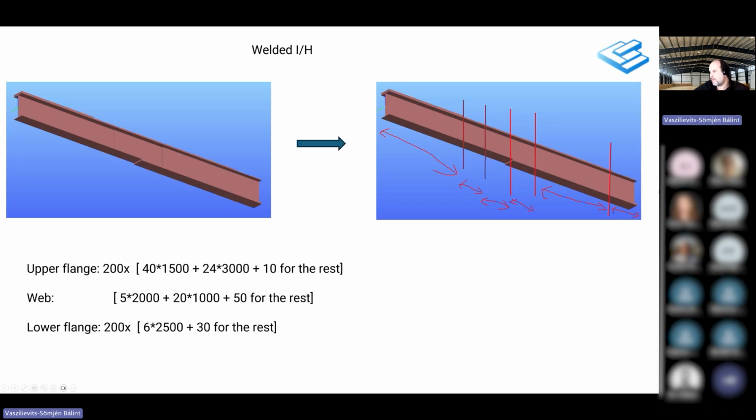Place them on the same reference line, solve the problem of eccentricities because these are strongly monosymmetric. When I place them, the same situation happens, that they will be automatically adjusted by the reference line, which is the center of gravity, which is not in the middle of the profile. Therefore, it looks very messy when I first made it. Up to now in Consteel, I had to calculate these shift values by hand and adjust them back to the right location. And then I was happy as long as I didn't want to change anything.